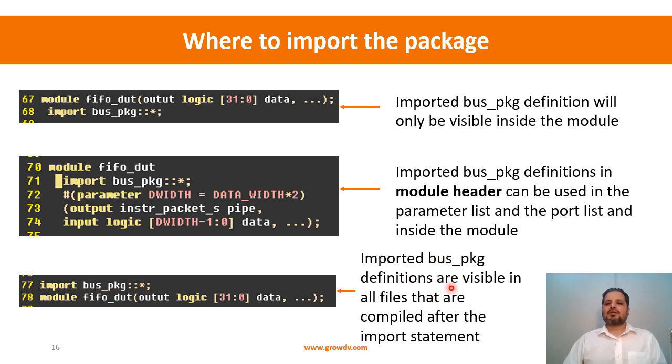The imported bus package definition will be visible to all the files that are compiled after the import statement. So if I have multiple module definitions that get compiled, all of them will be able to see the content of the package. Typically the good practice is that you keep it restricted to who needs it, rather than exposing things to everyone.